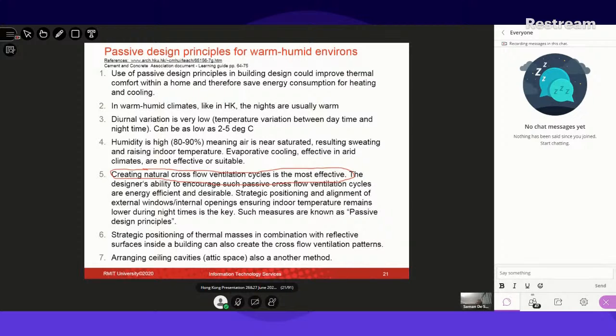In one part of the house, windows must be openable. The cooler side of the house can have lower louvers rather than upper louvers, and the hotter summer side can have the upper louvers, so that the cross ventilation can be really good. In the interior layout of your house, because you are now designing, you can make sure that the doors effectively allow the cross ventilation to go across your house, not through a passage or corridor.